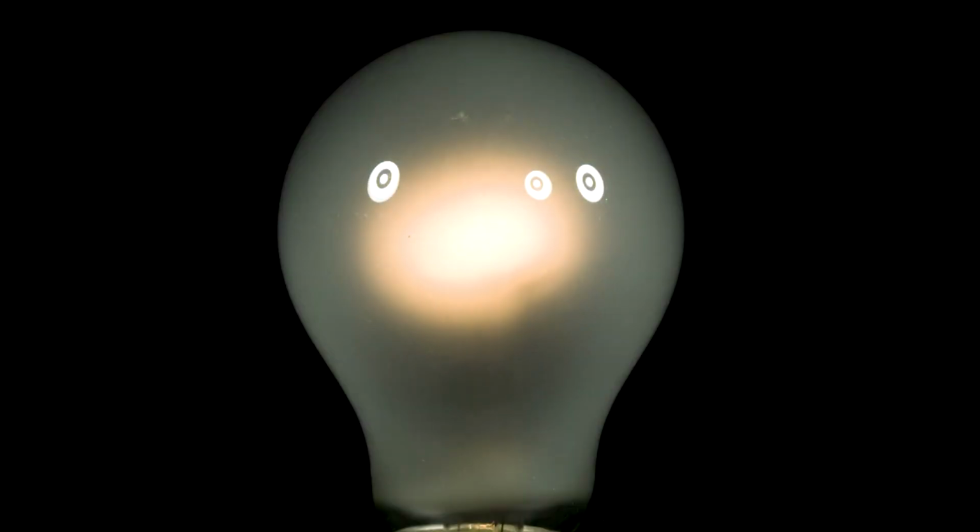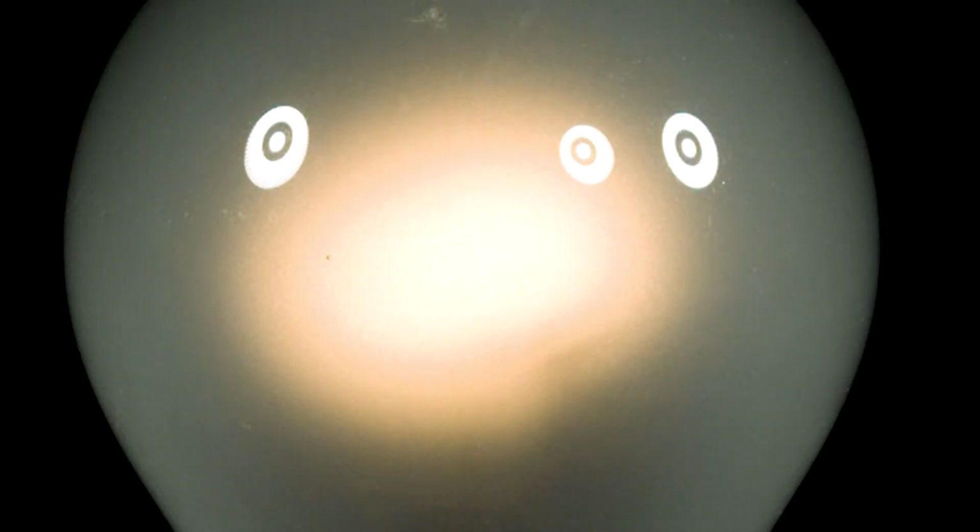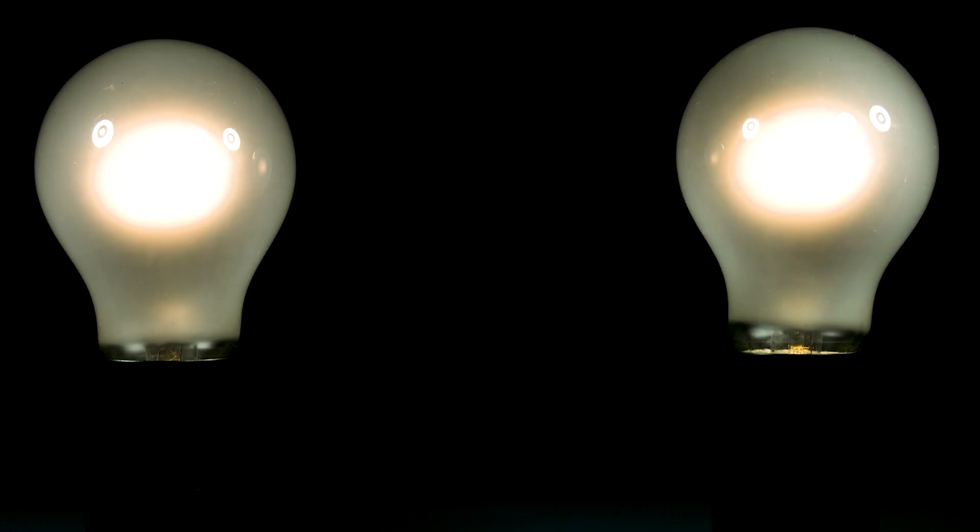Now here's the same light bulb, but the frame rate is cranked up to about 3,500 frames per second, so you can really see the pulsating a little more clearly. Also, I had to play with the lighting quite a bit, so I turned down the studio lights so that you could see a little bit more of the internal glowing from the filament. So here are two light bulbs side by side. You can clearly see that the pulsating is in lockstep with each other. And that's because all of the outlets in your house have the same frequency of the voltage waveform, and also they're in the same phase. That means the crests and the troughs of all the outlets on a single circuit are all lined up with one another. So that's why the pulsating is in lockstep.